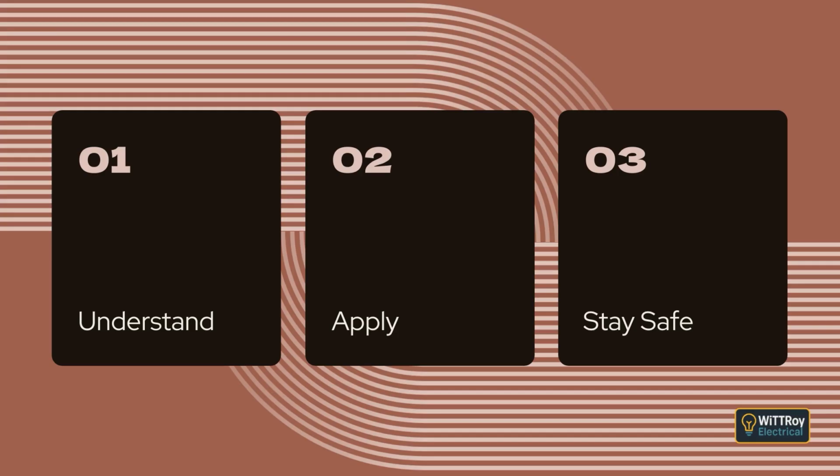In places with more than one electrical installation inside the same building, the main switchboard cannot be hidden inside one tenancy or one private area. It has to be in a shared location so that it is available for everyone who needs access, including emergency services.